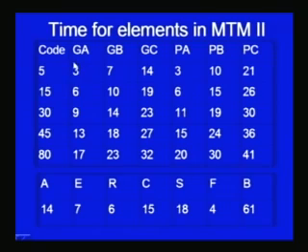And if we see here, these values indicate the time required for performing the motion. Get A is 3 TMU for distances travelled less than 5 centimeter. Performing the get under B conditions, which are slightly difficult, the time required is 7 TMU for distances less than 5 centimeter. So, with increasing degree of difficulty, the time required for performing the motion increases for the same distance.